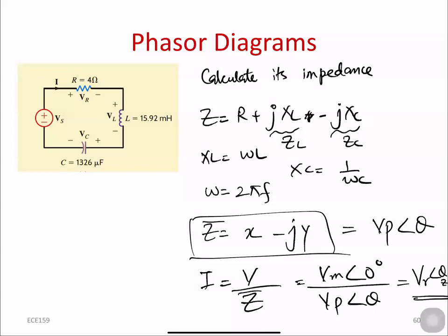Once you have this value calculated, you can easily plot this on a phasor diagram, right? Whatever the value is here, you can plot this theta z here, and this is going to be the magnitude for this vector. For any circuit, this is the way you have to solve this phasor diagram. Thank you very much.